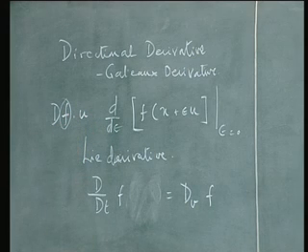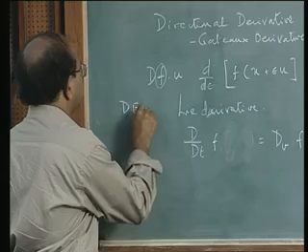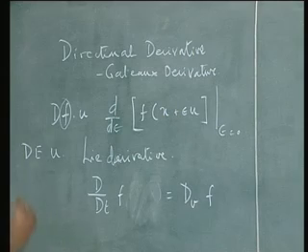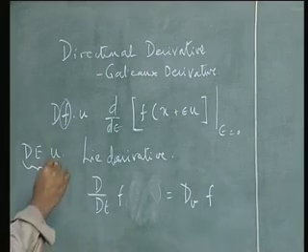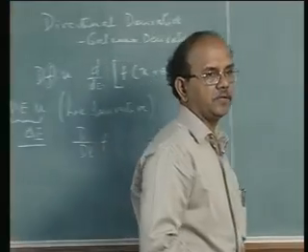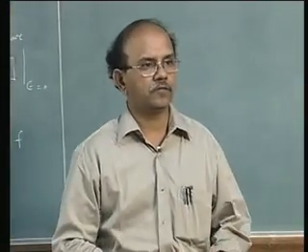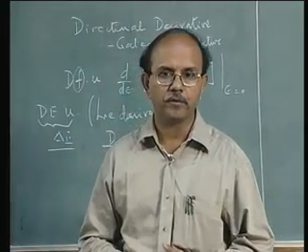u. We said that this is very useful for us to progress with linearization, and we saw, for example, that the directional derivative of E, dE dot u along the direction of u, is nothing but an increase, and that we called delta E and so on. Now please note that we had also defined what is called the Lie derivative or Lie time derivative. And we said that the Lie time derivative is obtained by a series of 3 operations. Hope all of you remember what these operations are. Pullback operation, determine the material derivative, and then push forward operation.